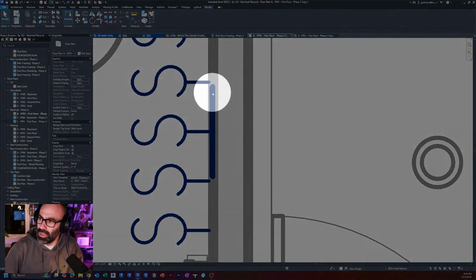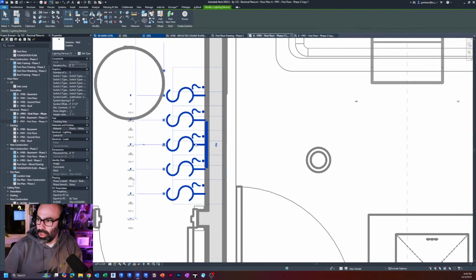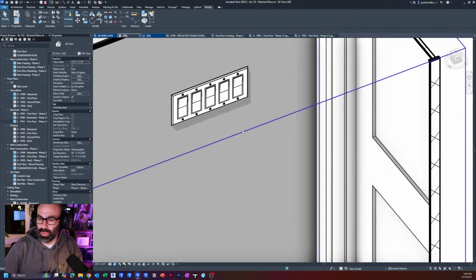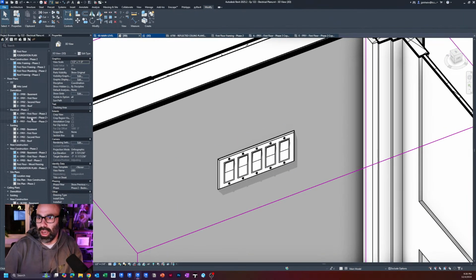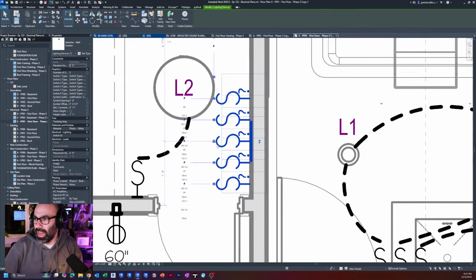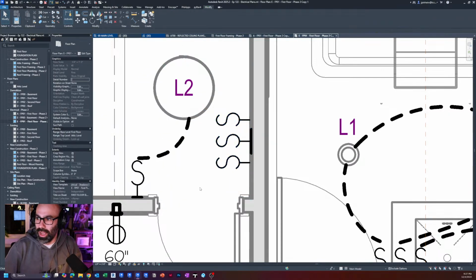But if you look closely, you can see that line there. Graphically, they look correct, so you have symbols that look good, but then three-dimensionally, you can see there's a 6 bank. So again, it makes this stupid simple to do. And each of these has a connector and does its thing. So the shortcut here is using a floor plan with an underlay as a simple way to get to a power and electrical plan, and then using the right families.